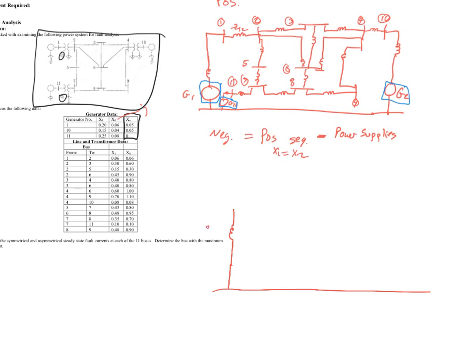So this is going to be 3 times the xn value there because it's non-zero. And we're also going to have whatever impedance is internal into the generator. Okay? So this one right here would be essentially the x0 value that you would have for generator 1. There's no power supplies, so at this point we can actually show that we have bus 1 at this point.